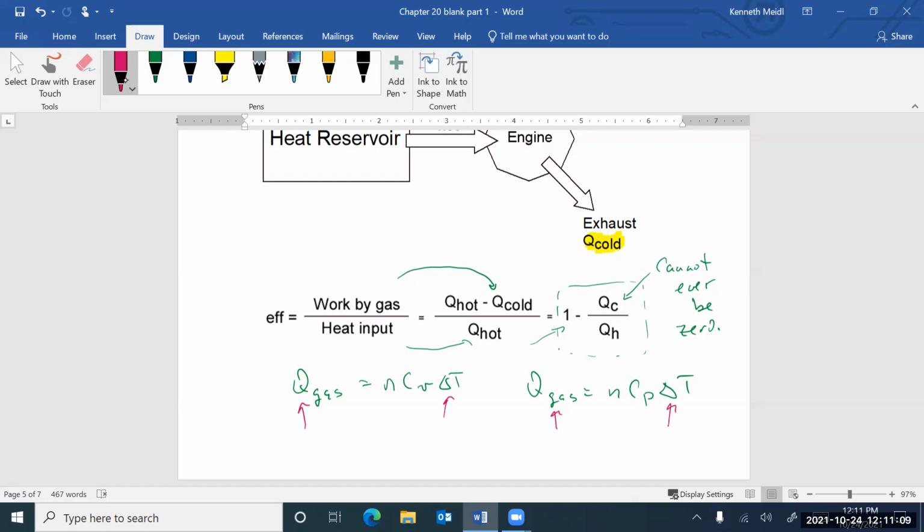And so there's this very beautiful argument in your textbook. A lot of times in lecture, I'll go through it step for step for step. We'll look at the Carnot cycle, and it usually takes about an hour to go through each step. And you end up with efficiency equaling something else than what we've got right here. But I think you can see very quickly that Q's are proportional to T's, no matter how you look at the gas. And so those Q's eventually could be taken out of this efficiency definition and temperatures can be put in.